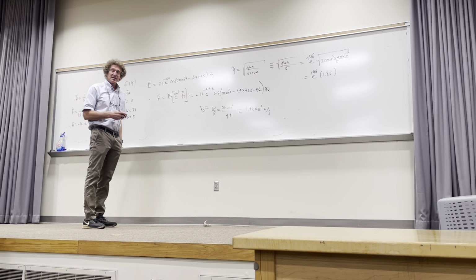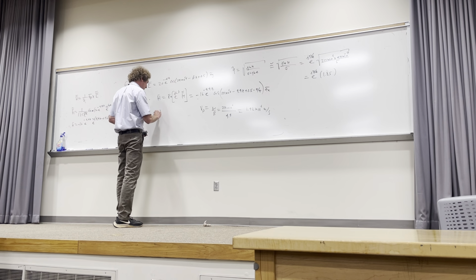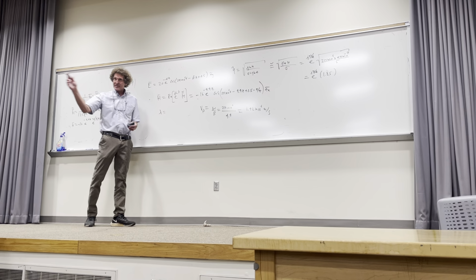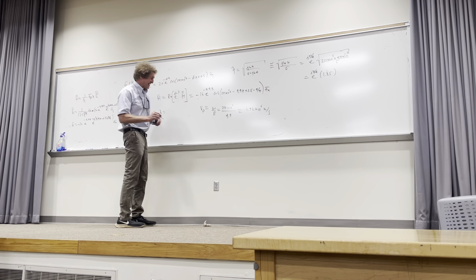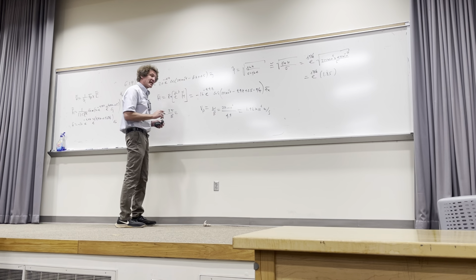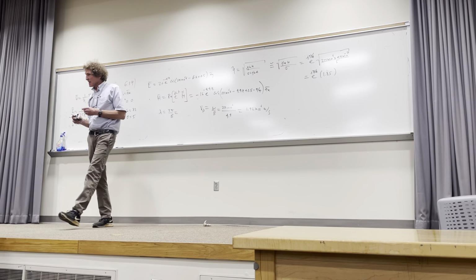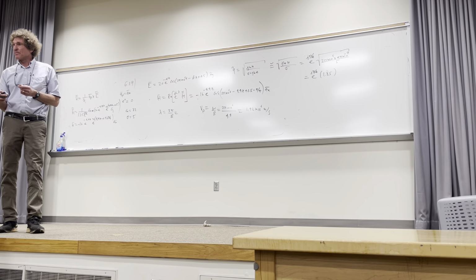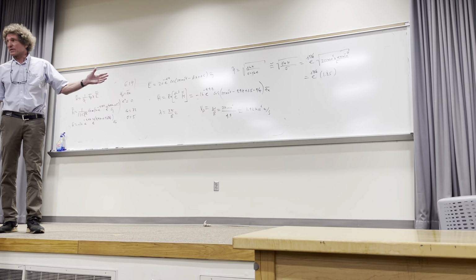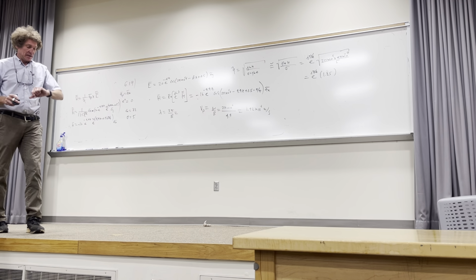Just for kicks, how do you get wavelength? He's right. Don't use c over f. It's 2 pi divided by beta, right? Now beta in this case is 4.4 as well. All right, so that's a no-brainer. But in free space, the wavelength would be much, much more. Okay.